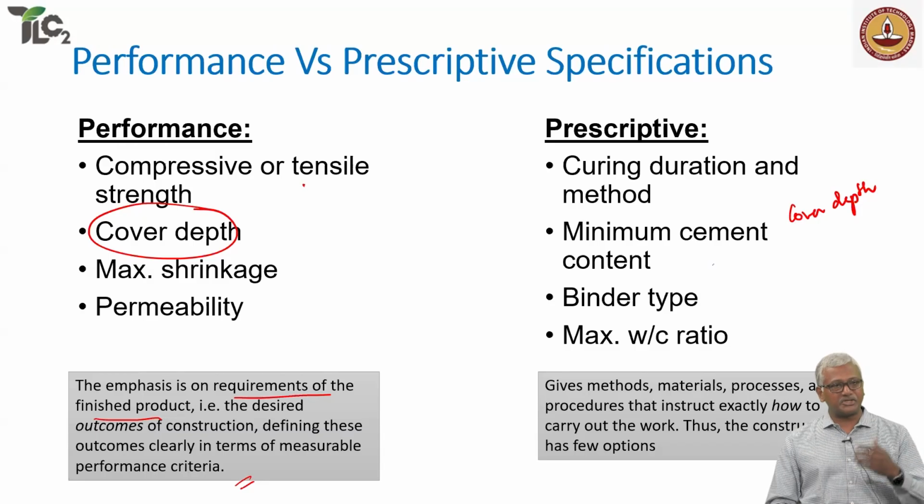Concrete in the structure is already shrunk. Right? No, pulse velocity is only giving us some indication of the soundness of the concrete in terms of whether the voids are properly closed because of proper compaction or not. UPV is not going to give you anything about shrinkage or permeability, right? You have to actually test these parameters. Unfortunately, by then it's already too late. You can't do anything. So the issue with performance specification is how to implement it.